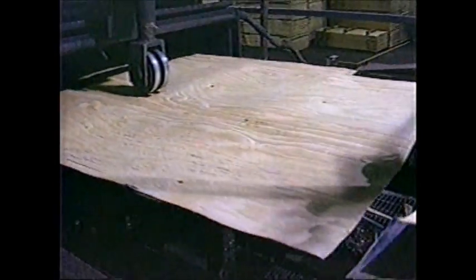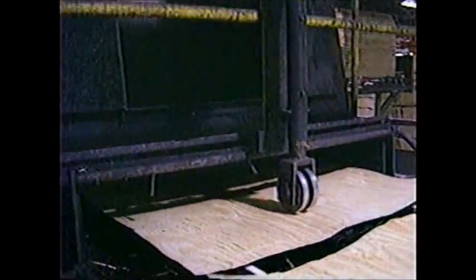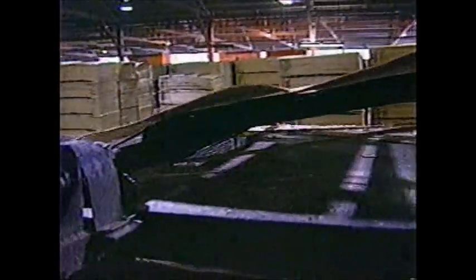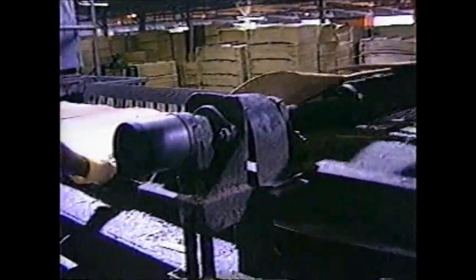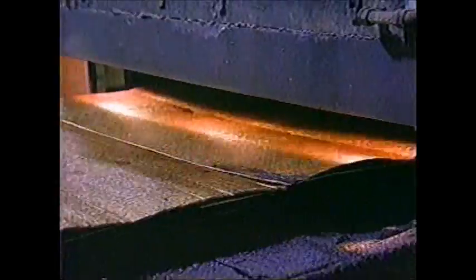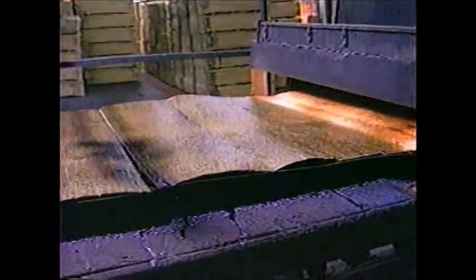A full-size panel back is first placed on the conveyor. It passes under a spray head, which lays down a coat of phenyl formaldehyde resin. A crossband of narrow random width stock is laid down next, with the wood grain at right angles to the bottom sheet. Adhesive is sprayed on the crossbands, and the core ply is placed over the bands with the grain of the core parallel to the back ply and at right angles to the crossband ply.